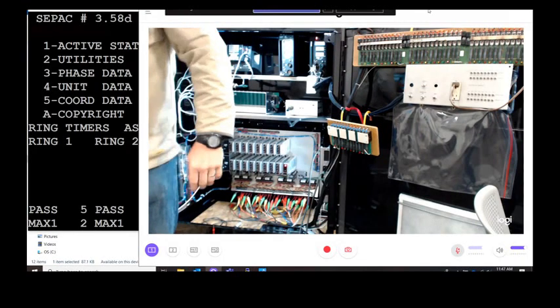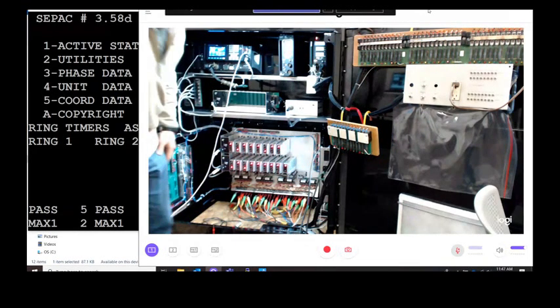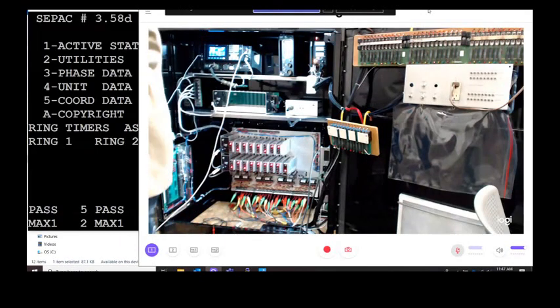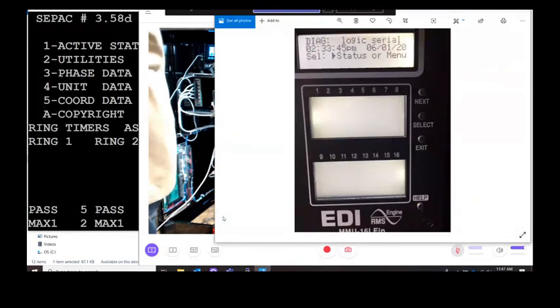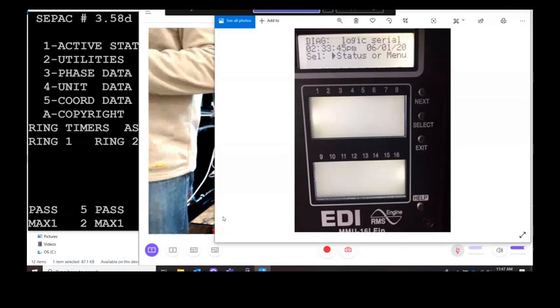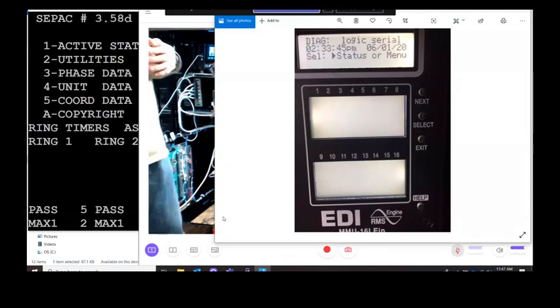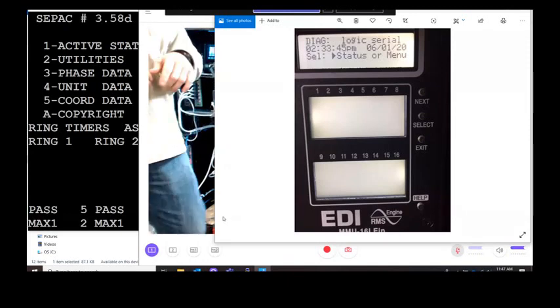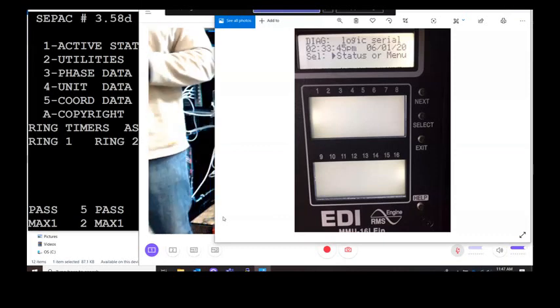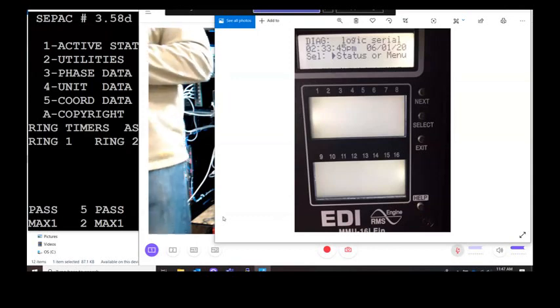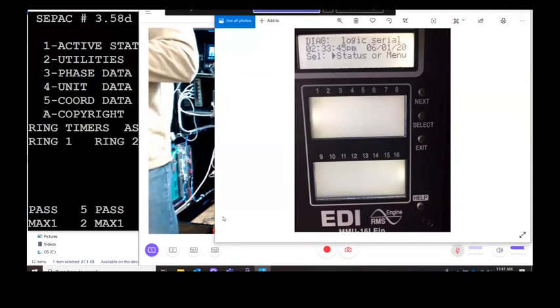Go back to video. All right. So I have a bad MMU, a known bad, we have to send it back for repair. I put that in there, and basically here's the error message that it has on. Diagnostic logic 0. If you come out to an intersection, it's in flash, and you look at that, instantaneously, you know you've got a bad MMU, something failed inside, something got burned up inside, just replace it. There's nothing you can do for it. Send it back to us.